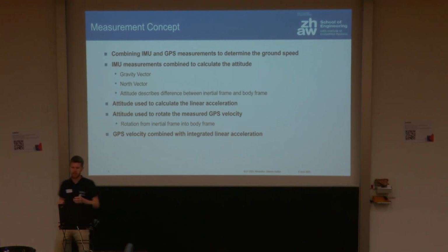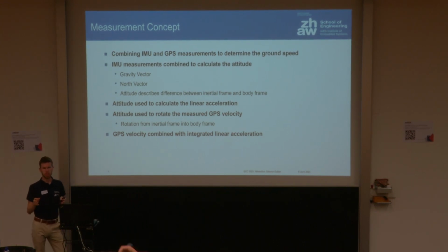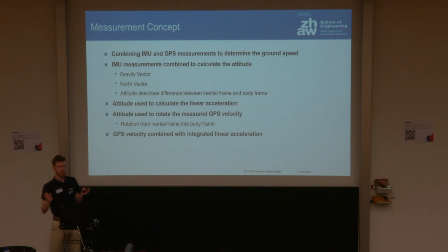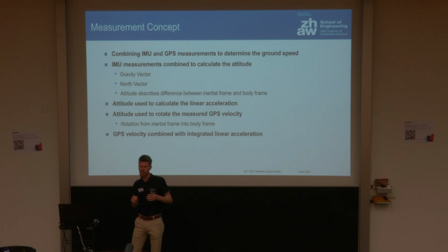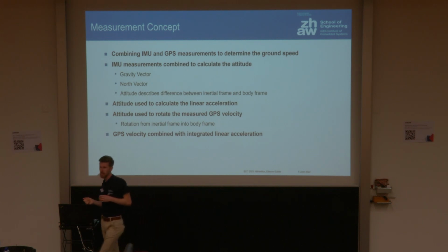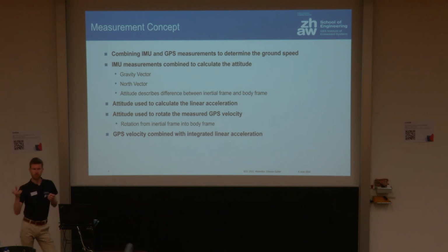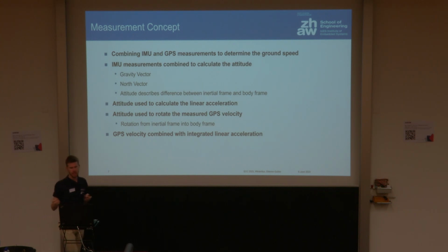The first one is an IMU, an inertial measurement unit, which consists of three sensors in one. It measures acceleration, it measures the rate of rotation, and it is also capable of finding the magnetic north pole, so it's also a magnetometer. This IMU is mostly used to figure out how an object, or the sensor which is attached to the object, is located in space.